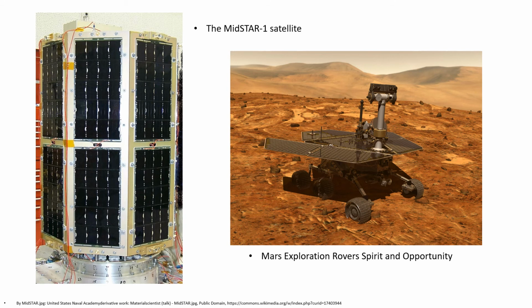In the later years after the 90s, dual and triple junction solar cells based on gallium arsenide with germanium and indium gallium phosphide layers were developed, which demonstrated a record efficiency of 32% and can operate with solar concentrators of light as high as 2000 suns. The Mars exploration rovers Spirit and Opportunity, meant to explore the Mars surface, were powered by gallium arsenide solar cells. Also, many of the solar cars utilize gallium arsenide in the solar arrays.